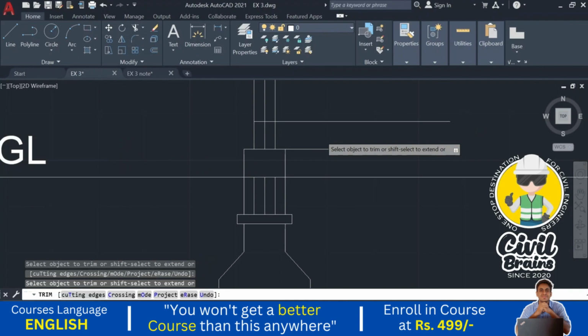So the slope we need to provide, or I just write here the total depth is 0.6 meter, and square footing, the total depth is 0.6 meter, and it will be reduced to slope at 0.3 meter depth.